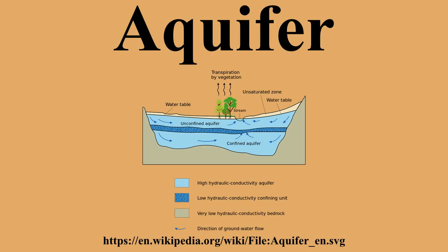Aquifers versus aquitards. Aquifers are typically saturated regions of the subsurface that produce an economically feasible quantity of water to a well or spring. An aquitard is a zone within the earth that restricts the flow of groundwater from one aquifer to another. A completely impermeable aquitard is called an aquiclude or aquifuge. Aquitards comprise layers of either clay or non-porous rock with low hydraulic conductivity.